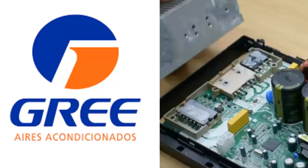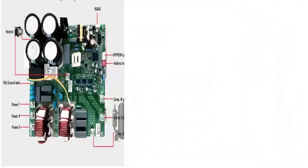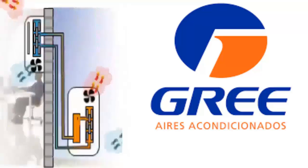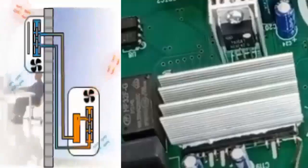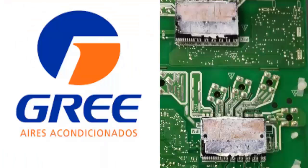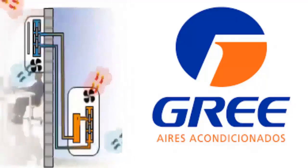As a final recommendation, before intervening with the external unit's electronic board to search for component failures, it is highly advisable to visually check if the heat exchanger or fins of the IPM module are in the correct position and to check the condition of the thermal paste. This is important because loose fins can hinder heat dissipation, increasing the temperature of the electronic module and triggering the H5 error code. Some recommendations to resolve this fault code are: